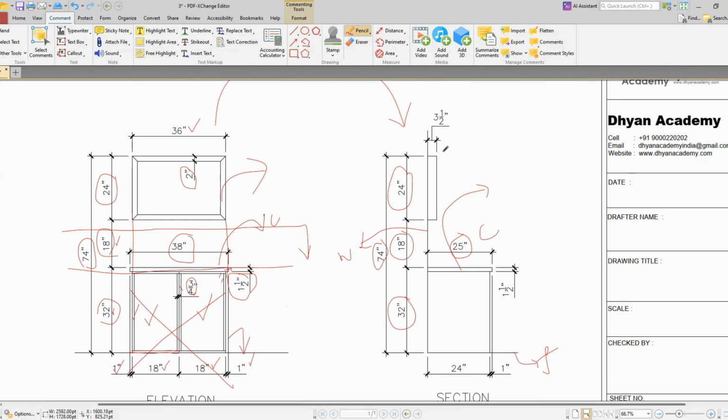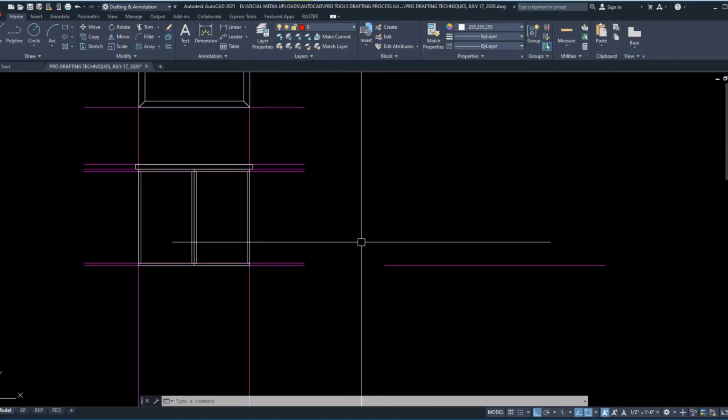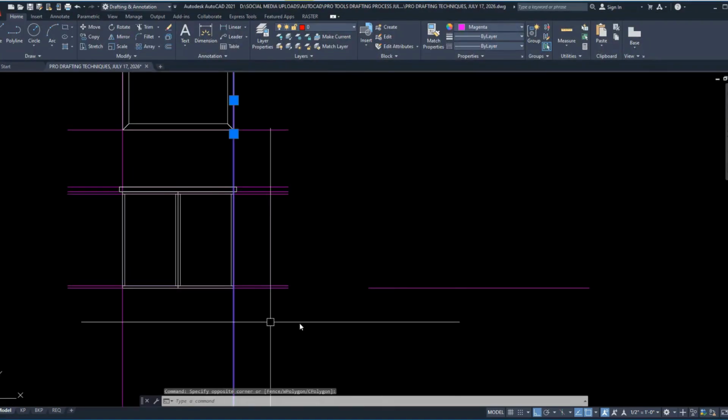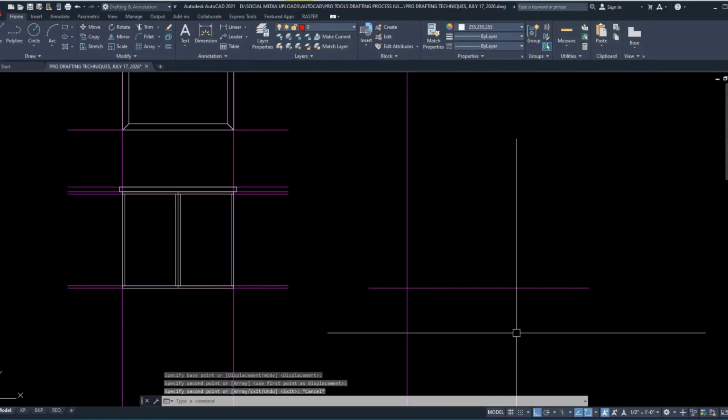So here we are trying to create this, the depth of this trim or frame is 3.5 inches. That means exactly at this height you have to develop this, and you have to create this countertop side view, and you have to give a 1 inch gap, and then you have to create the side view of the open cabinet. Okay, so now let's come back to it, because I have all the dimensions, so it's already traced, nothing to worry.